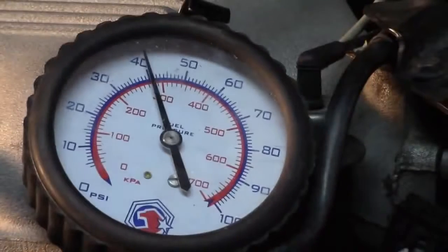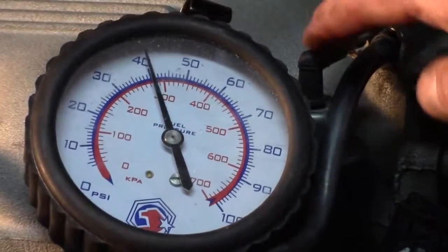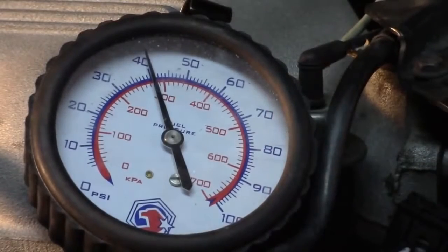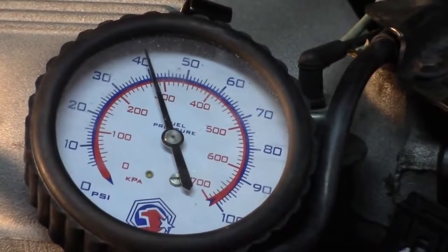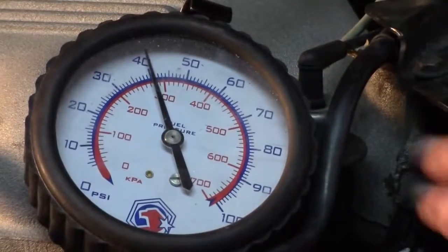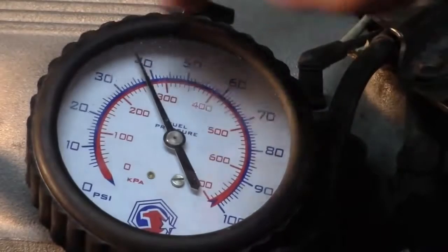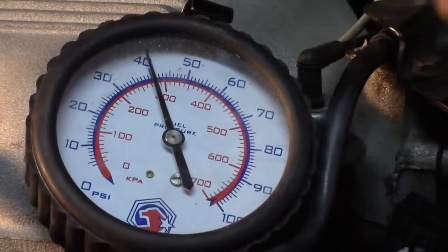Another good test that you can do is also the snap throttle test. Now think on a snap throttle, we're going to open wide open, removing vacuum from the fuel pressure regulator. That should cause a highest point on our fuel pressure gauge. But then, of course, on decel, that would be the highest possible engine vacuum you can get, which should actually lower the gauge just a little bit because of the additional vacuum further closing the regulator. So let's see what happens. And that's indeed what happens. It's going to go up and then down and stabilize back again at 40. So this indicates definite proper operation of our fuel pressure regulator, very much so with that test.